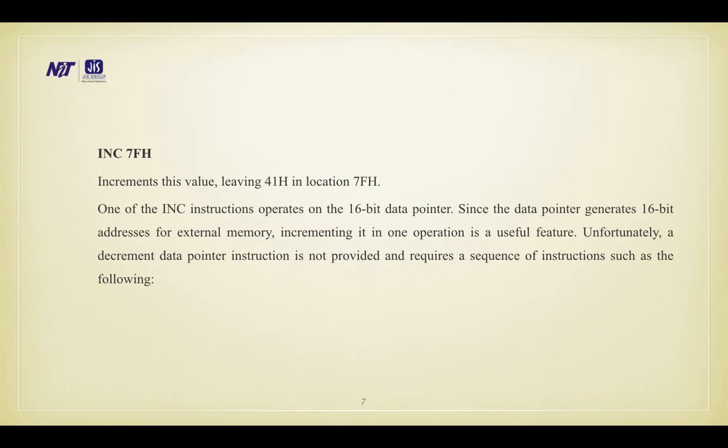The INC instruction also operates on the 16-bit data pointer. Since the data pointer generates 16-bit addresses for external memory, incrementing it in one operation is a useful feature. Unfortunately, a decrement data pointer instruction is not provided and requires a sequence of instructions such as the following: